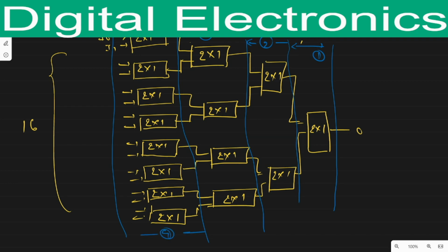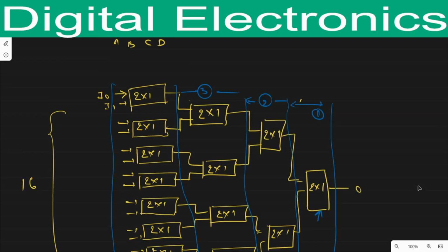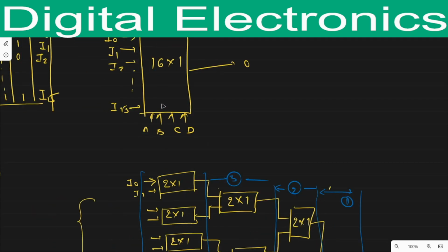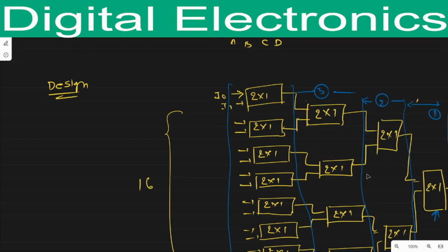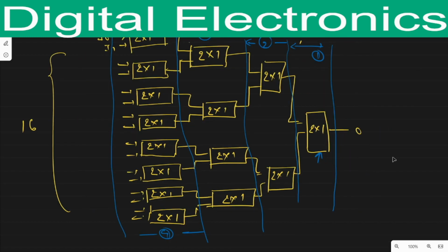The multiplexer that provides the output always contains the selection line that is LSB. It means that in the truth table this D is the LSB and this A is the MSB. So the multiplexer that is close to the output will contain the selection line LSB.